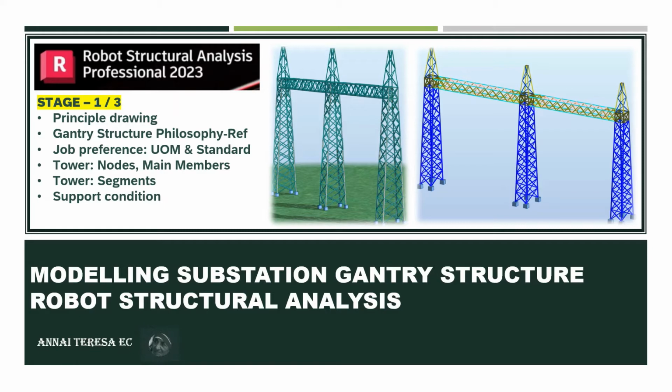Next is the tower segments. Based upon the splice and bracing pattern, we are going to divide the entire tower model into various segments. And finally, the support condition we are going to fix for the tower base. So these are the main contents we are going to discuss in this stage 1 of 3.